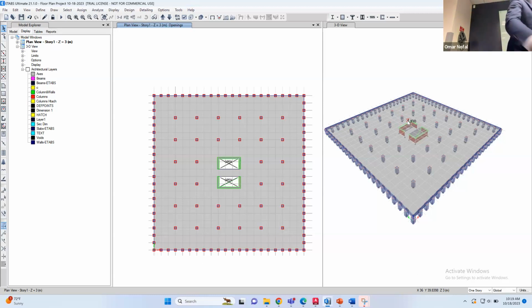So, as we said last time, this is my shear wall. And it's a very big element, not a frame. If you put a frame element, just the line connecting this joint with this joint is not going to be stiff enough for this to feel it. So what we do, we make a shell element with the depth of the beam and the length of the beam that connects these two walls at each story, something like this. That's how we model a coupling beam.